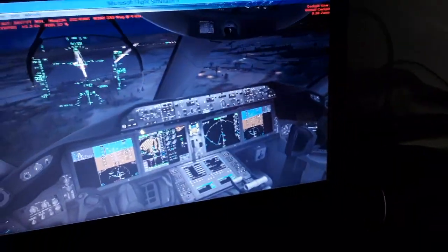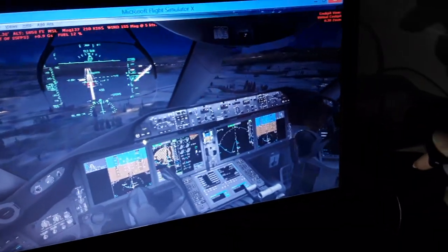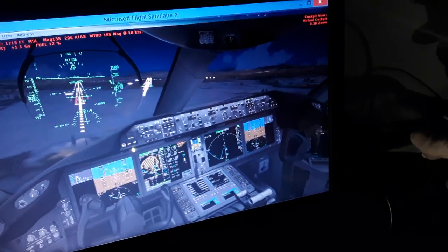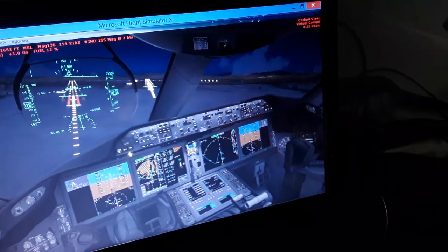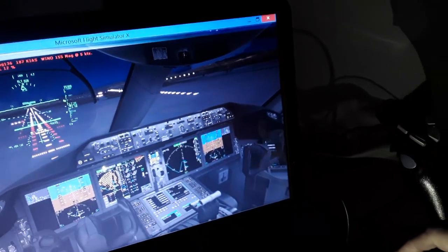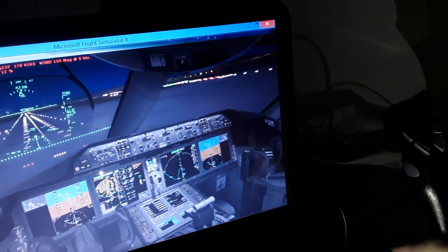We have the Lszh localizer here, as you can see, to follow all the indications. Also in front of us, as you can see, we fly manually. Some side wind, some wind gust. We use all flight controls to align with the runway. We're going to have some side wind and some wind gusts and some thrust. For the touchdown, we're going to be leveling off, align with the center line and level off for the flare.